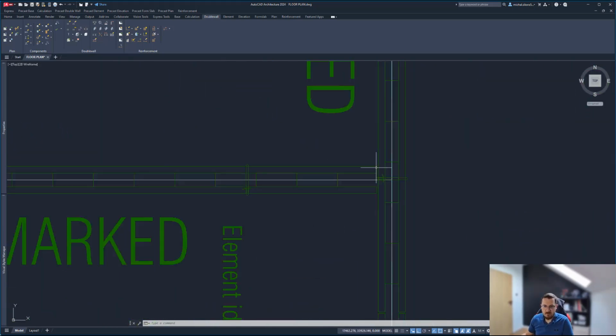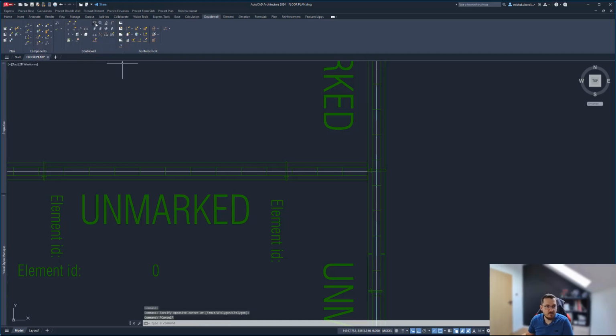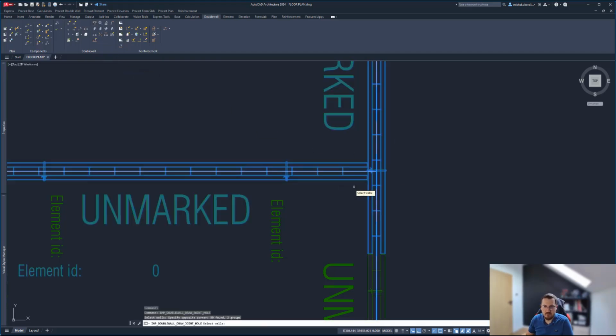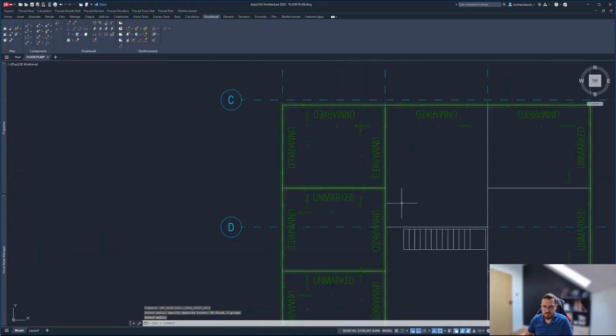Okay, with that, let me go ahead and, for example, create a connection between this wall and this wall, because this requires a T connection between those. So let me select those two walls, like so. And I have a bunch of options here. It automatically detects that we have a T connection between double walls, and we can either create a slit, we can create an open hole throughout both panels, or we can add a U-bar and a slit for a different type of concreting, different type of connection. For us, I'll just use a slit and not make it a cut through the whole height of the panel. So it's just going to be a slit in a wall, which we'll see. So I'm just going to accept that, and there's that slit.